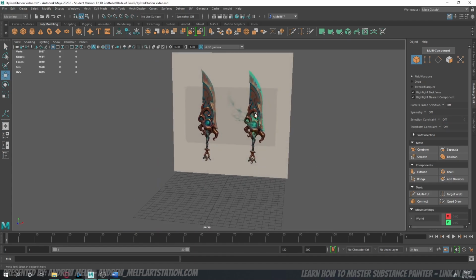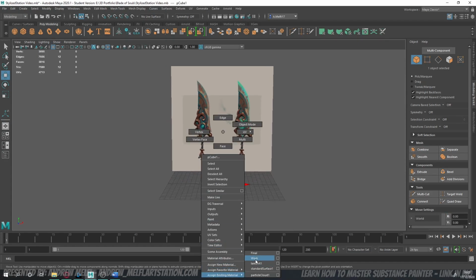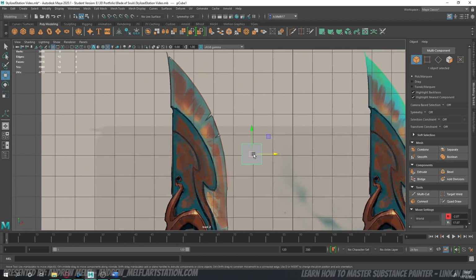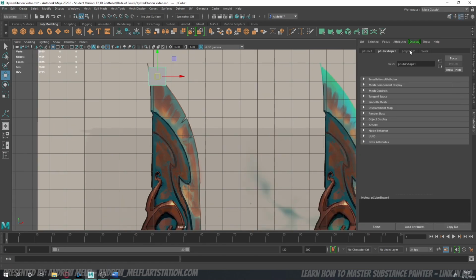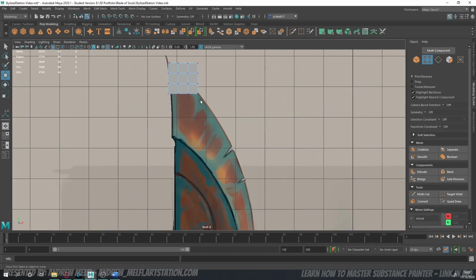What I actually used to create the blade is just a simple shape. Just get a cube, change the material. Drag that up, go to the front view again, drag that to the top, and make sure the corners are aligned. I also want to add more subdivisions, so I'll bump them up to 3. I'll leave the bottom one as 1 because that's just the side. Now I just need to drag these vertices down, making sure they're somewhat straight across the blade.